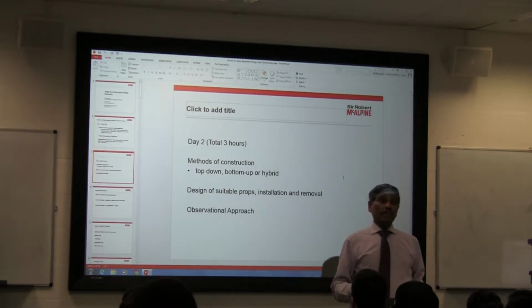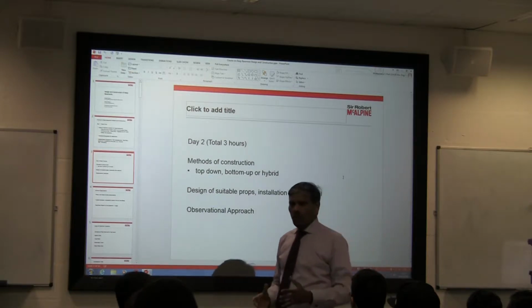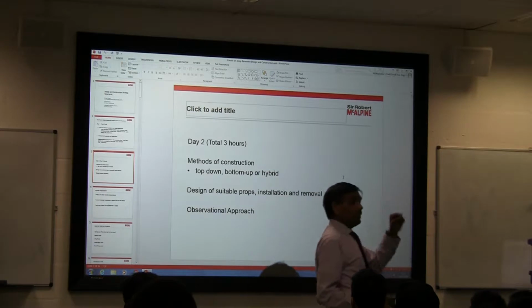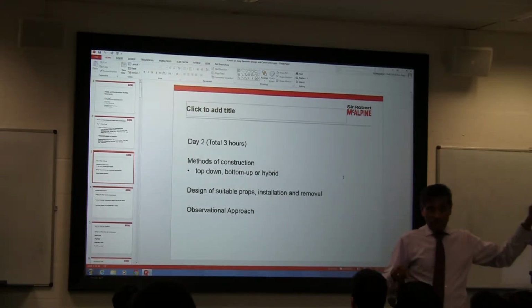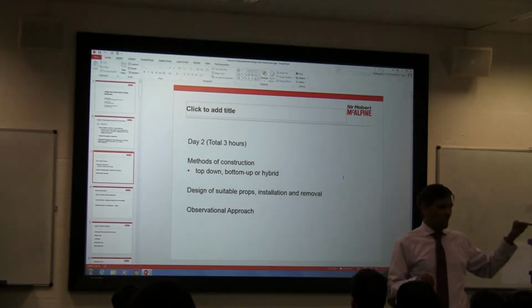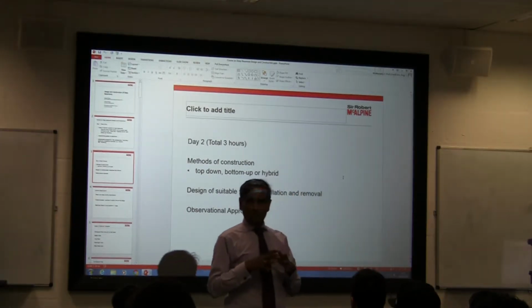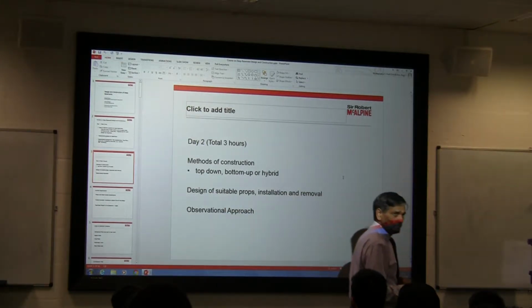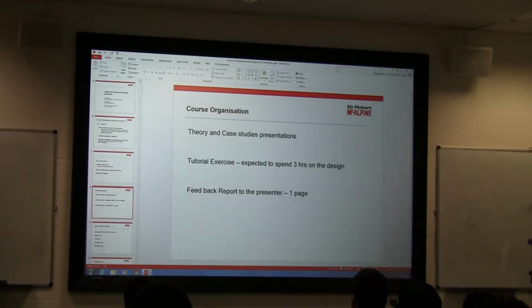That is why it is very important we have the observational approach. We give them confidence. What are we monitoring? We tell them. We keep everybody informed. We should say, look, before we started digging, we are taking the readings now. We're going to dig and monitor, and then we keep informing you what is happening. And that's very important, keeping everybody in the same place, keeping everybody informed of what is happening. Make sense? So that's called the observational approach.